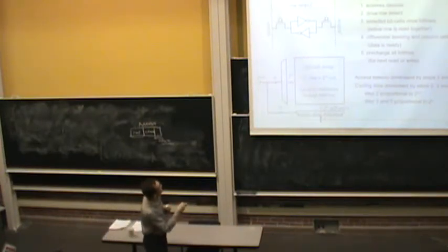I will not go through this in detail, but the read sequence is very similar to what I described here. You read the entire row, and we have 2 bit lines. There's circuitry here that senses the 2 bit lines and essentially selects the column, which are the sense amplifiers and the mux here, and then you pre-charge all bit lines.